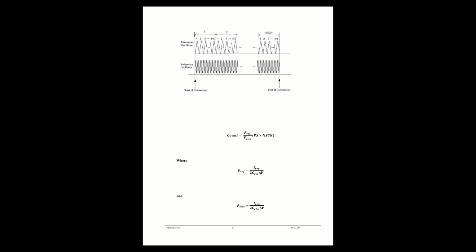So in the notes, I describe what values I have set for these. And this was all done experimentally with the K65. I just sat there and looked at counts and the touch pads and tried to find a reasonable value for these parameters. What I did first was set up this reference so that it was at the highest frequency that was usable.